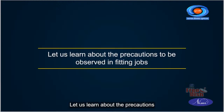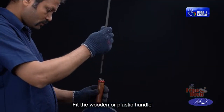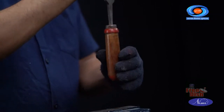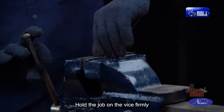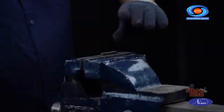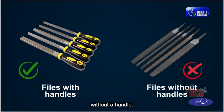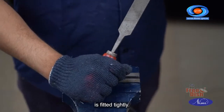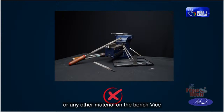Let us learn about the precautions to be observed in fitting jobs. Fit the wooden or plastic handle for the files. Hold the job on the vise firmly. Do not use the file without a handle. Check whether the handle of the file is fitted tightly. Avoid storing of tools or any other material on the bench vise.